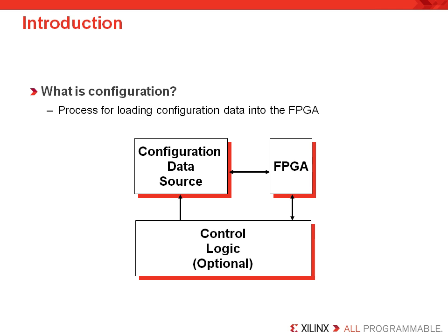Like processors and processor peripherals, Xilinx FPGAs can be reprogrammed in system, on demand, and an unlimited number of times. In fact, some customers take advantage of the reconfigurable nature of FPGAs to the extent that they have multiple bitstreams loaded onto their system. This feature is referred to as multi-boot. Multi-boot can save the cost of purchasing another FPGA or even a larger ASIC.